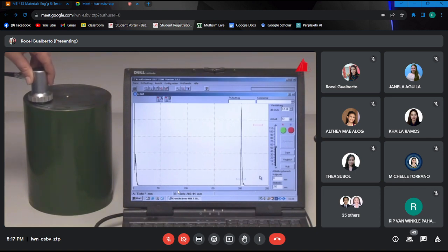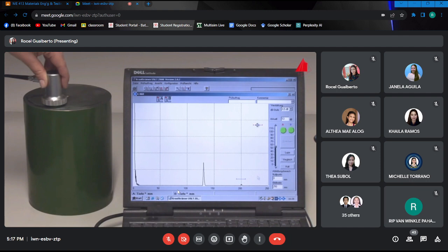The material tester scans the upper front end of the cylinder with a probe and observes the monitor. A defect echo appears on the monitor. This defect is located in a depth of 130 millimeters below the surface.